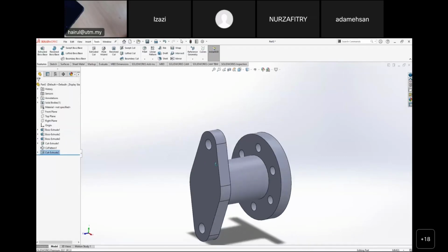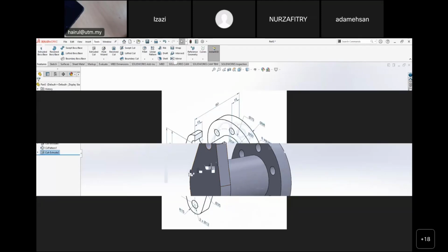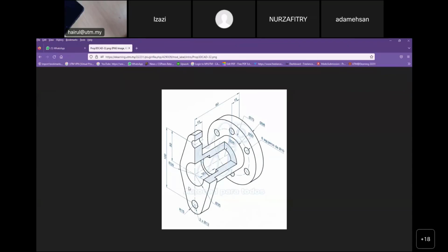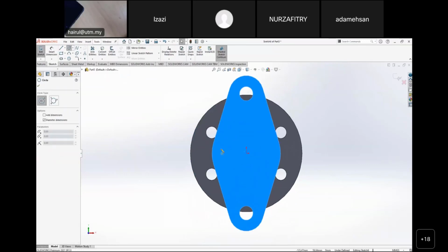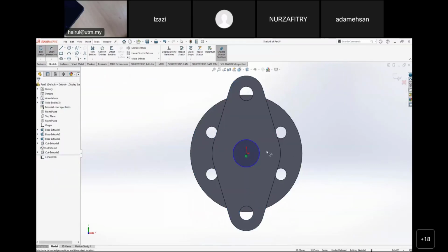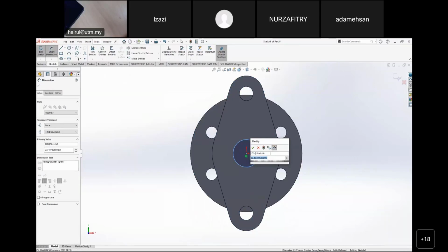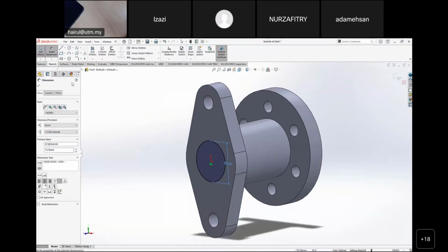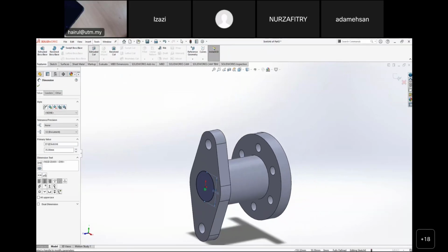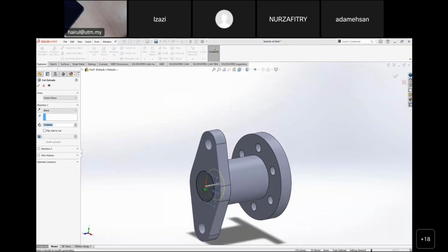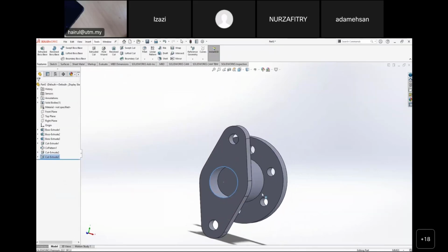Okay. Cut there. Okay, what about this one? What about the inside? Cut extrude, another step 30, cut extrude again. That's how we do it. Okay, this one is cut extrude of the distance 30, with diameter here 35, right? Here we have a diameter at the center point. Diameter is 35. To be features extruded cut of a distance 30. That's one extruded cut.